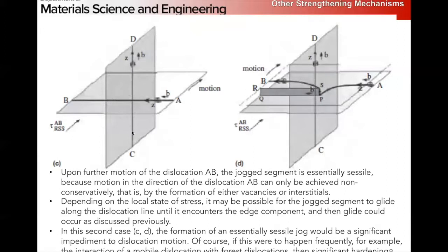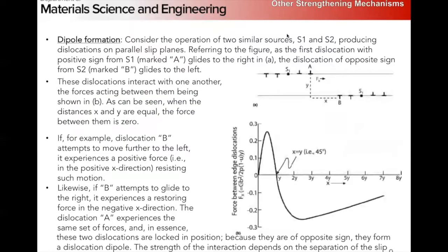We call these dislocations that run through the slip plane like this, that are vertical through the slip plane, the general term for these we call forest dislocations, and we call this mechanism of these dislocations interacting with the forest dislocations and creating jogs, forest hardening. It's the general term. So if you hear the word forest hardening, this is what we're talking about. But any dislocation that has a screw component, which means the screw part of a dislocation loop or partials, we're going to have a significant impediment to motion from jog formation.